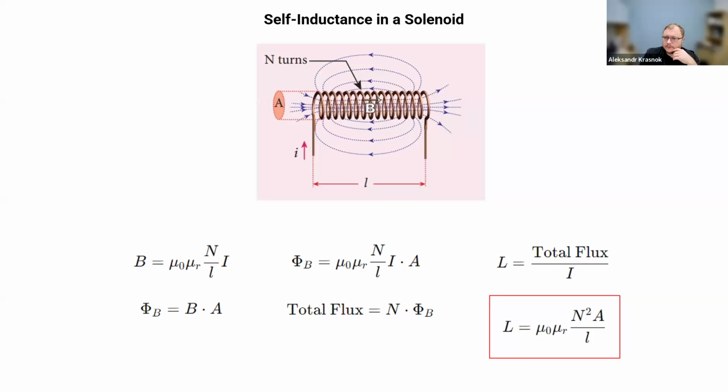So if your goal is to increase this inductance as much as possible, you need to make more turns, because a twice larger number of turns gives a 4 times larger inductance.